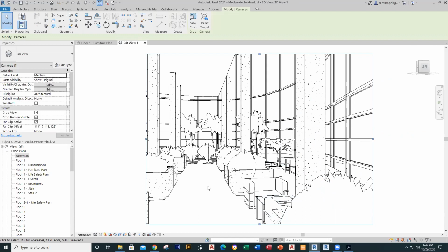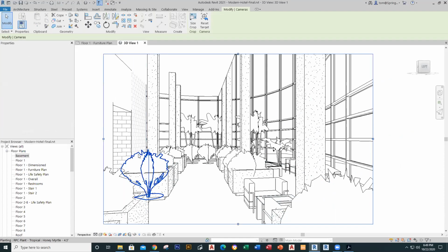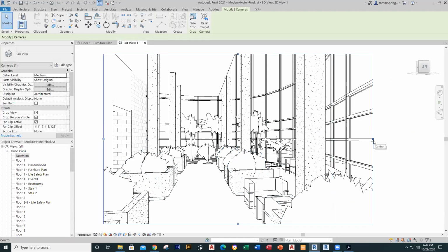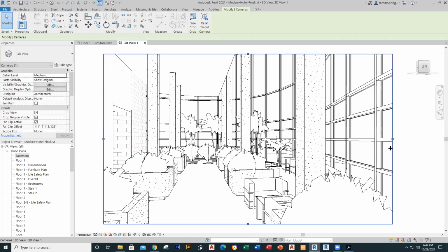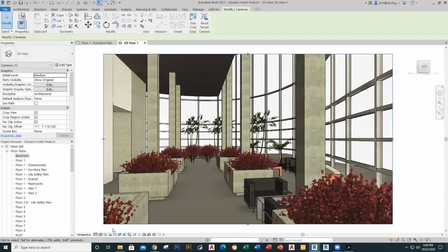Yes. Okay. So you're looking at the interior view, and you can actually open this up by grabbing these handles right here and pulling them from side to side. And as you do this, now you're taking a look at this really nice atrium area. What we're going to do right now is use our view control down here and choose realistic, just to see what it looks like when we turn the detail on. And it gives you this kind of view here.